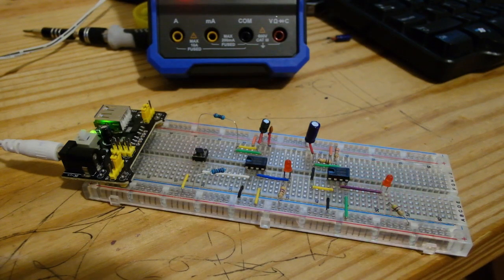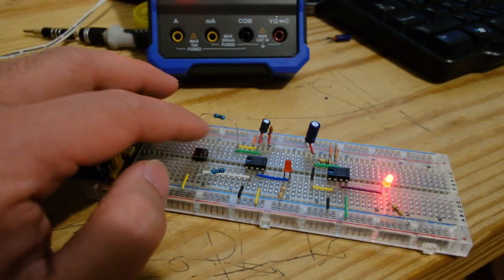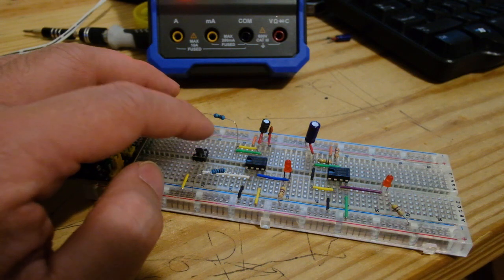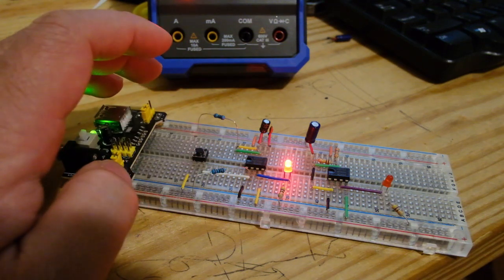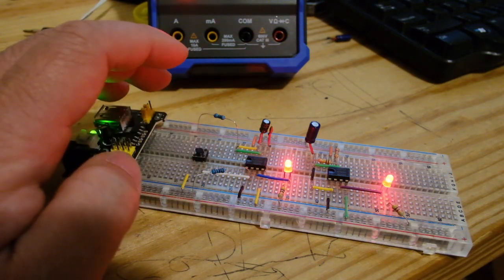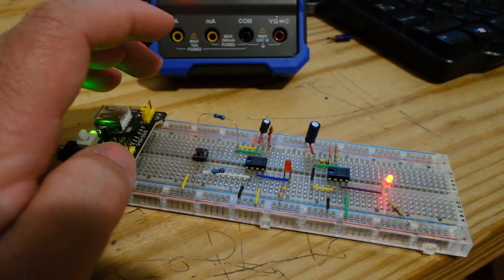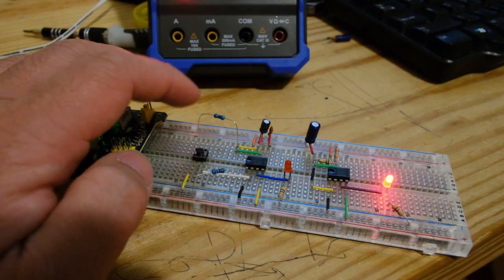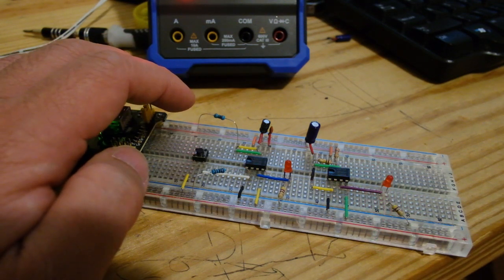Our first experiment involves the monostable circuit configuration, where we will not only generate pulses of specific duration but also incorporate LEDs to visualize the output. By connecting resistors and capacitors in a specific configuration, we can precisely control the timing of the pulse. This allows us to explore applications such as push-button timers, one-shot triggers, and more, all while observing the mesmerizing glow of the LEDs.